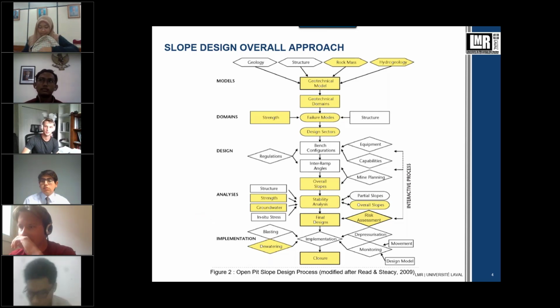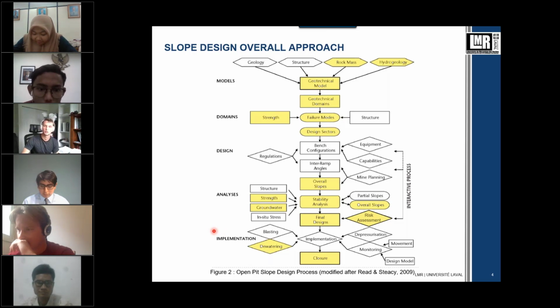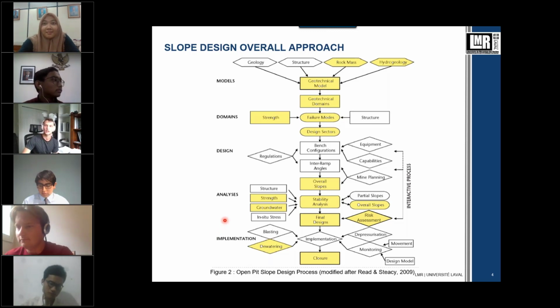The deterministic approach, based on the mean rock mass properties, allows calculating a factor of safety using the 2D numerical modeling code FLAC/Slope. For the probability of failure and the mean factor of safety, it was calculated using a Monte Carlo probabilistic approach using statistical distribution of the rock mass shear strength parameters. The 2D numerical modeling code RS2 was used for the probabilistic approach, and the results were compared with the FLAC/Slope for the deterministic factor of safety.